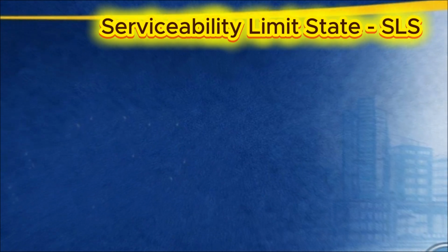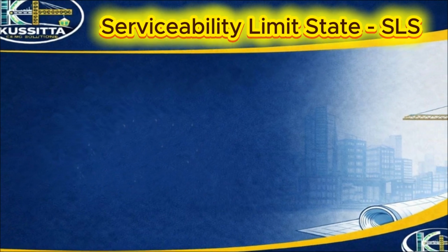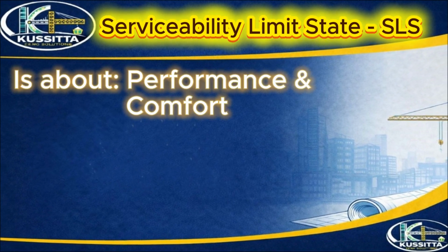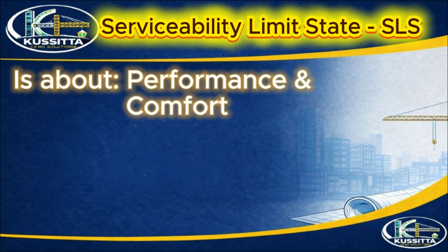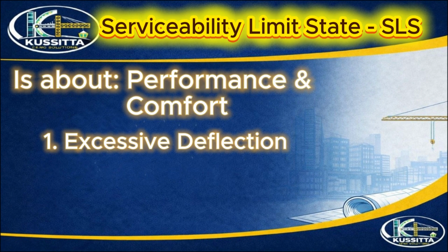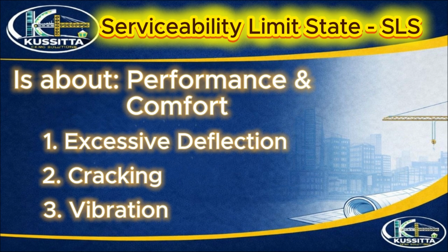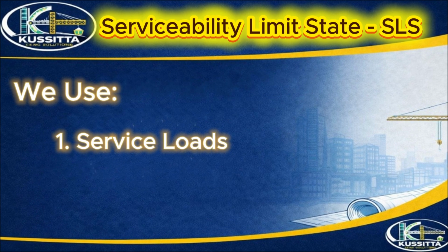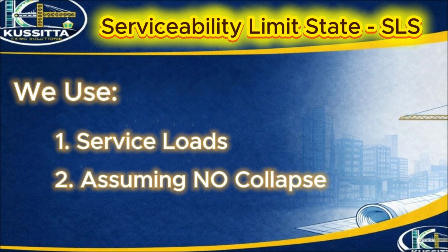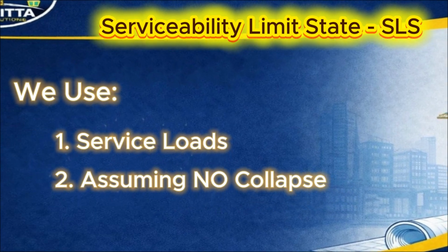Serviceability limit state, SLS: this is about performance and comfort. Examples: excessive deflection, cracking, and vibration. Here we use service loads and assume no collapse, but usability matters.